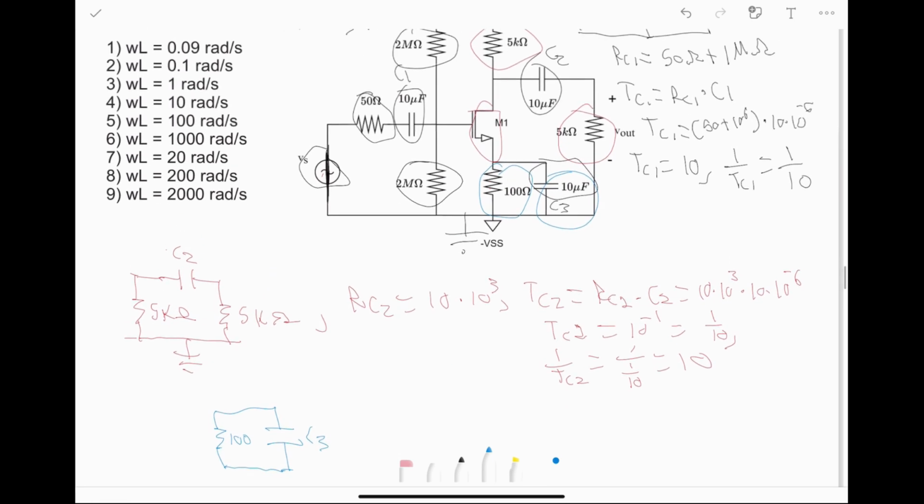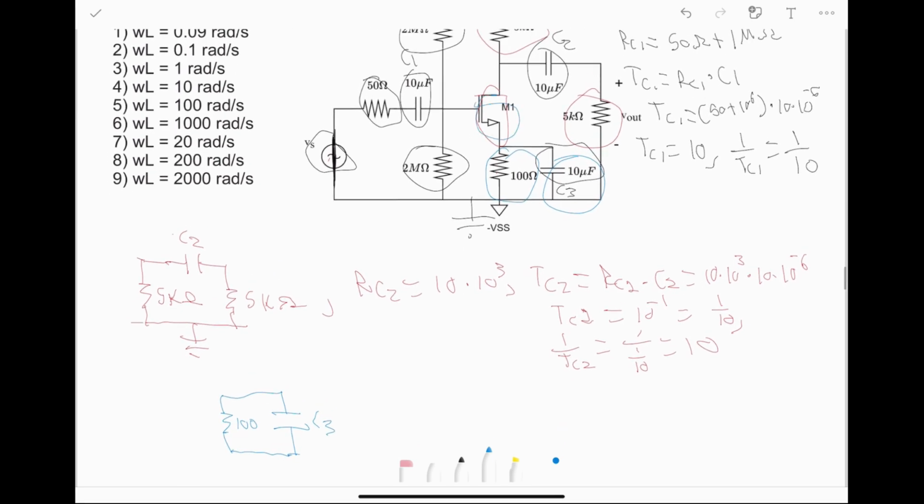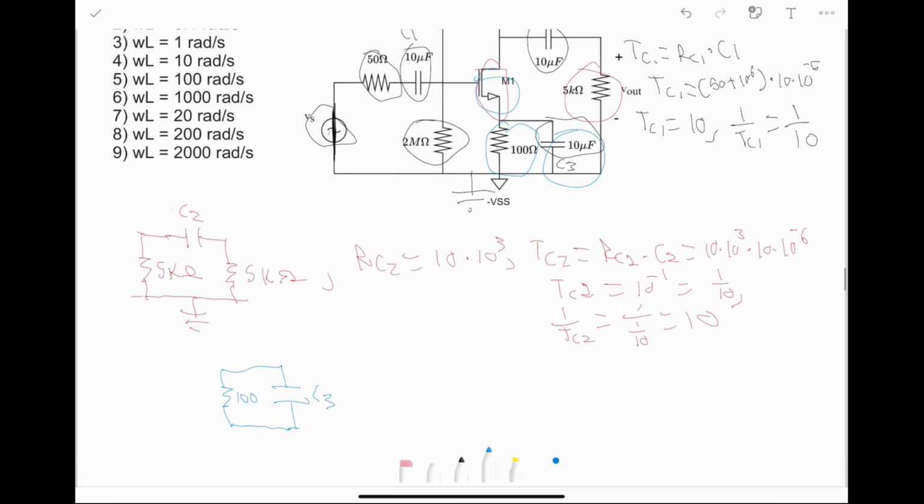And then we also have this MOSFET here, which actually does become relevant because the source of this NMOS is right here. So Vs is actually the same as the voltage across the capacitor. The reason that's important is because if this capacitor has a voltage on it, it actually changes what Vs is.